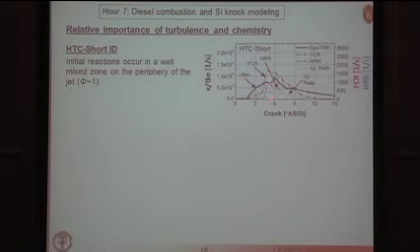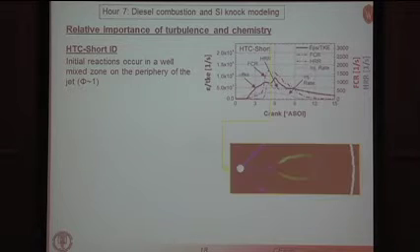That's associated with combustion-generated turbulence. And then, of course, everything dies away as we burn away the fuel. So that's what you see with the short ignition delay high temperature combustion. This is, again, just to remind you what that jet looks like at this time, right after the ignition takes place.